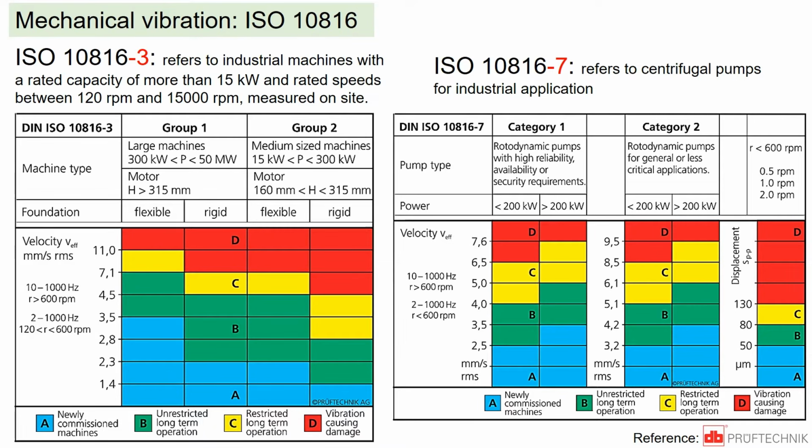Here is an example of vibration severity according to ISO standards. We'll delve deeper into this ISO spec in a different video. But the table provides an idea of when to inspect the machine upon exceeding vibration thresholds.